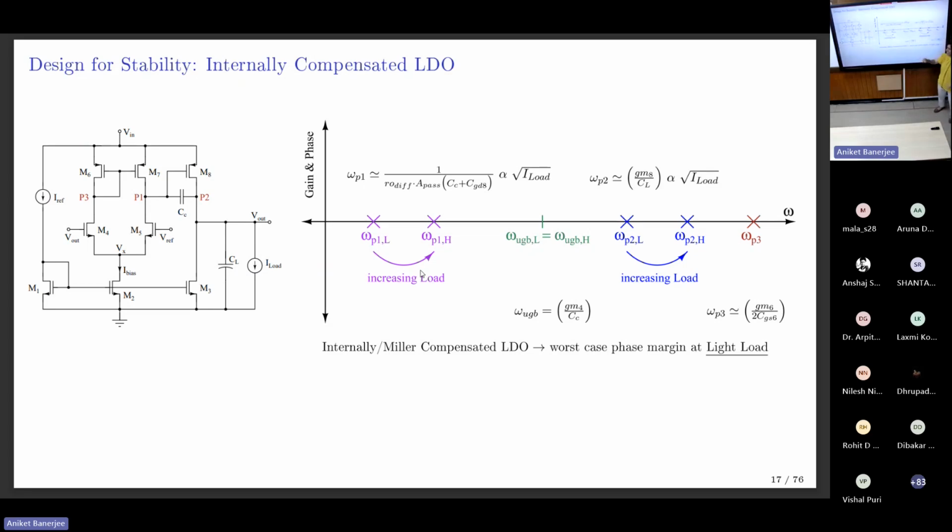Okay. So quickly again, I know I've sized M8, the power FET. That gives me all insights about the second port. As soon as I get that, I can fall backwards through the flow, get the unity gain bandwidth to the light load for 45-degree phase margin, and then step by step design the differential amplifier. And that's the work that Professor Manikandan will share with you. How do you marry the flow and the plots to design?